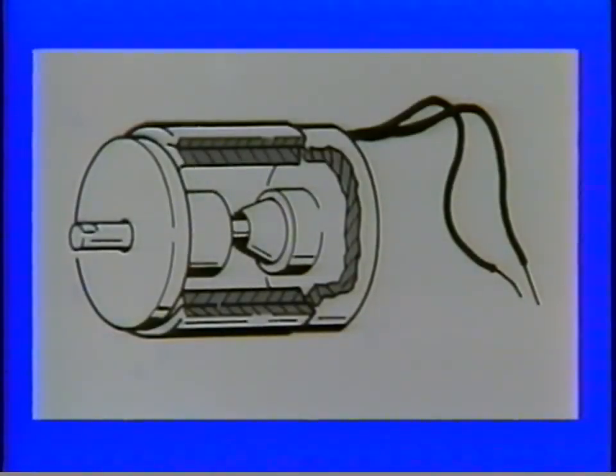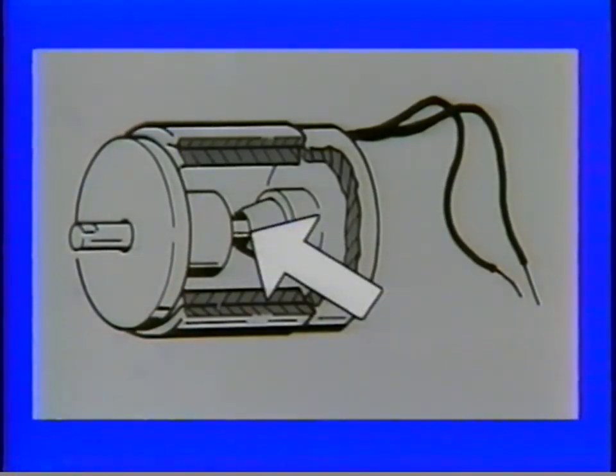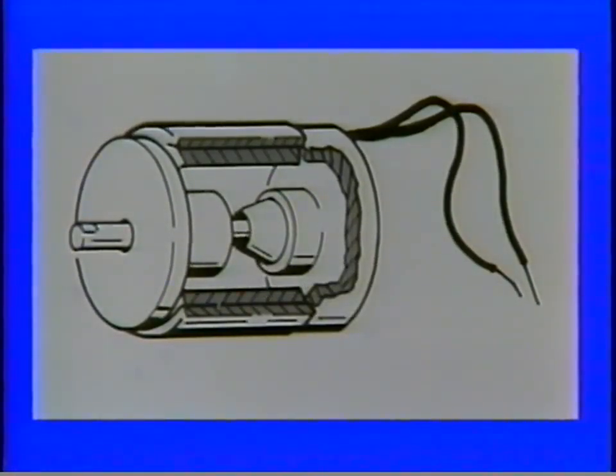The hammer solenoid consists of a coil and a plunger. A magnetic field is created when voltage is applied to the coil. The magnetic field pulls the plunger into the coil and causes the other end of the plunger to drive the print hammer. The print hammer moves to the rear and drives the character petal against the ribbon and paper. The printer board controls the impression of the characters by varying the current applied to the hammer solenoid.